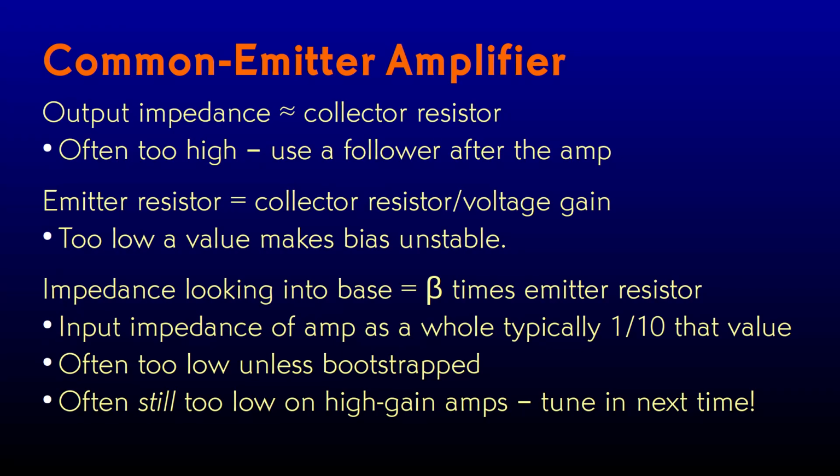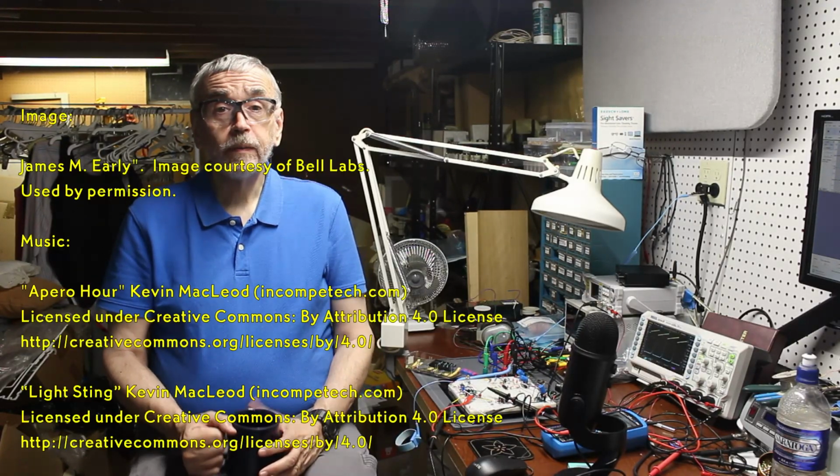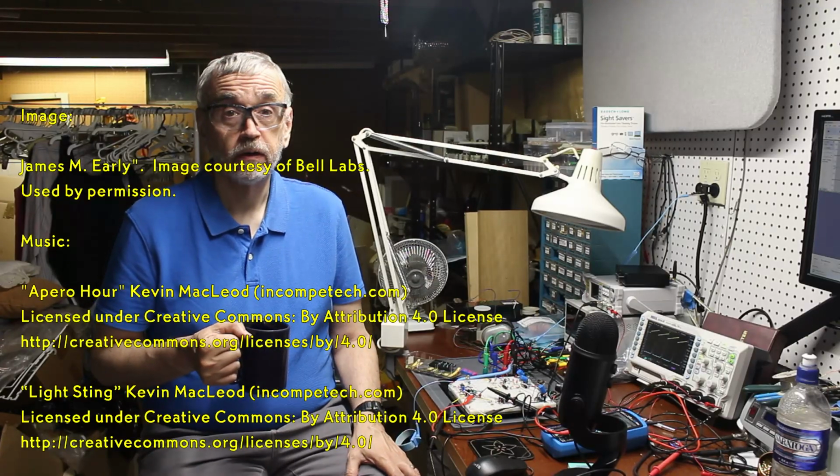The input impedance of the amplifier as a whole is typically much lower than that because the bias network eats up most of the input current. We can make that input impedance a little bit better by bootstrapping the divider network, but that still might not be good enough to match a very high impedance source. Next time, we'll look at an alternative to bootstrapping for dealing with high impedance sources, and go on a quest for higher input impedance and more circuit gain. We may get some surprises, so stay tuned for that.